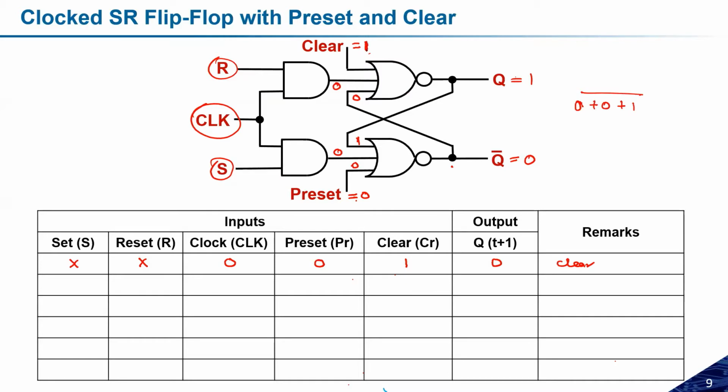So if I'm clearing over here, the clear will simply be 1 plus 0 plus 0 and the complement, that will become 0. So what it means, we will clear it and the rest will be complemented. So the next state here will be the complemented, but here it will be clear because we have activated this one. So the clear and preset inputs decide whether I have to clear or preset. Similarly, the next case would be if I activate the preset. So how will it happen?